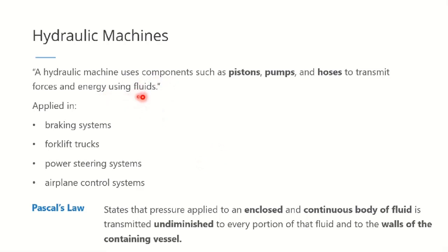Okay, so take note, ang fluids na involved dito is incompressible. Kasi hindi ka makakapag-transmit ng force kung compressible yung fluid na involved. So, pwedeng motor oil. So, pwede yun. Incompressible yun. Wag lang, for example, air. So, air is compressible. So, hindi mo siya pwedeng gamitin dito sa hydraulic machines.